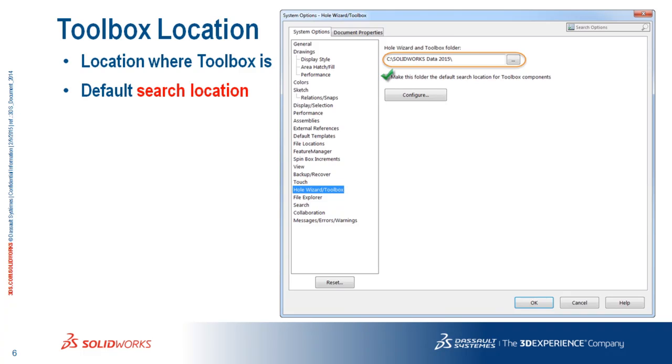Where it becomes tricky and interesting for users is they've decided, all right, I'm comfortable with this part. I made the size I want. Maybe it's a chunk of structural steel. It's probably where I see it the most. You configure it to a size that you want, and you save it off as your own part name, and you put it in your own library file somewhere. And the next time you open up your assembly, it doesn't work. And it goes back to some default size, or it's too big or too small, okay?